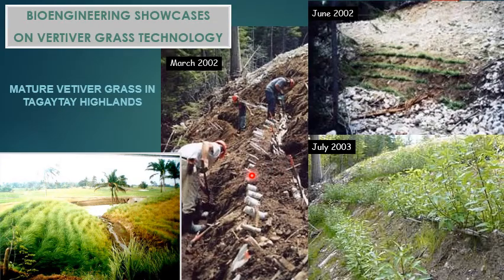The last slide is a technique or specialist field in geotechnical engineering. They call it bioengineering. In bioengineering, their favorite vegetation or grass is the vetiver. And this is a showcase of installation of vetiver grass in Tagaytay Highlands for slope stability.